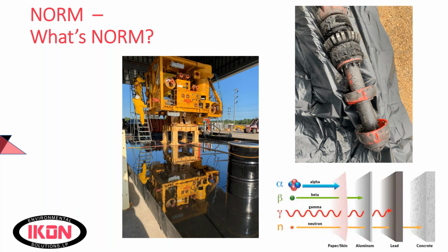It's whatever the density of that material is in there. Or if you have one small pile of pipe you walk up to and get, say, 40 microrem per hour, now you have 3 small piles of pipe, you're not necessarily going to get 120 microrem per hour because you have 3. You still may only get 40. So it really depends on how big your sample is you're measuring, what your detector geometry is, how close you are to it. And so there's a lot of factors that come into play. So pretty much you just have to survey a lot to properly characterize something.